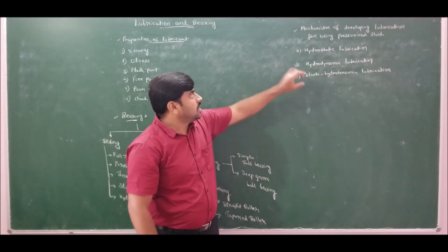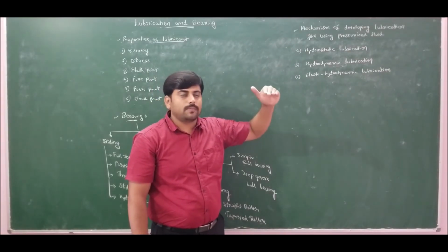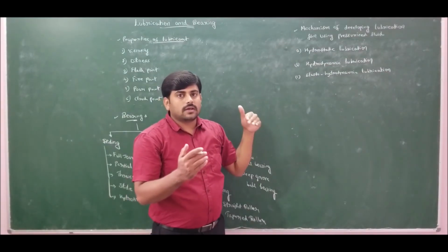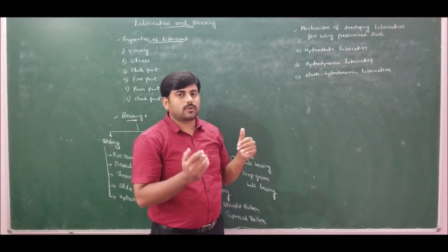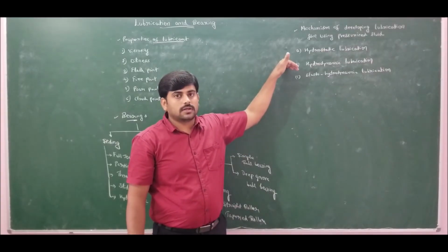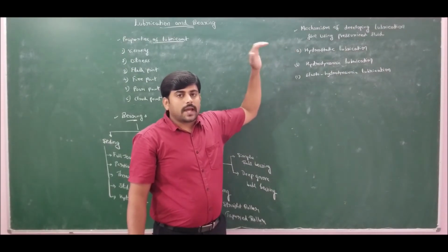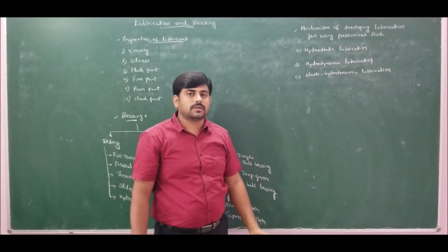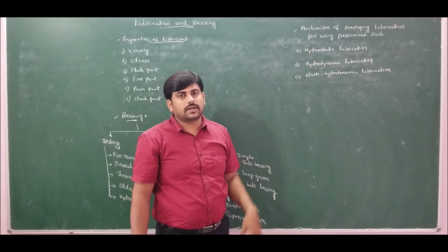So hence, the combination of these two will help us to provide proper lubrication. During starting and stopping, we can use hydrostatic lubrication. By using pressurized fluid, we can create the gap between the journal and bearing, thereby providing the thin film of lubrication. While running, we can use hydrodynamic lubrication. The disadvantage of hydrostatic lubrication is that it requires additional equipment, whereas hydrodynamic lubrication does not require any additional equipment to supply the pressurized fluid. So both have their own advantages and disadvantages.